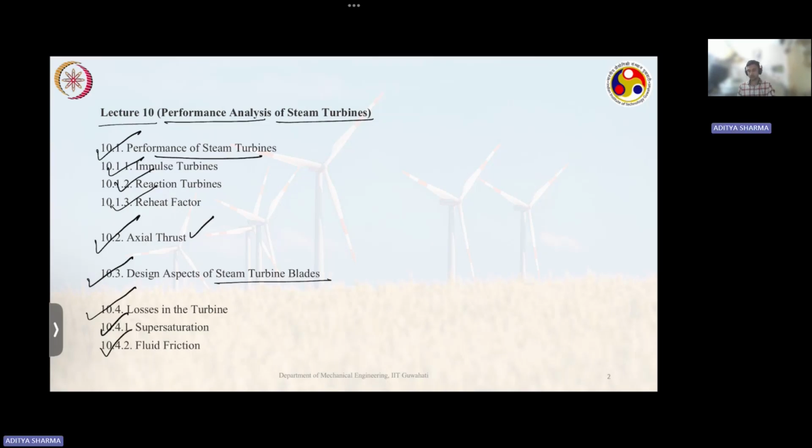If you see your nozzle, the friction in nozzle leads to your losses, right? And then there are different types of losses like fanning losses, admission losses, blade windage losses. So blade windage losses are basically because of eddies that the blades face, right?